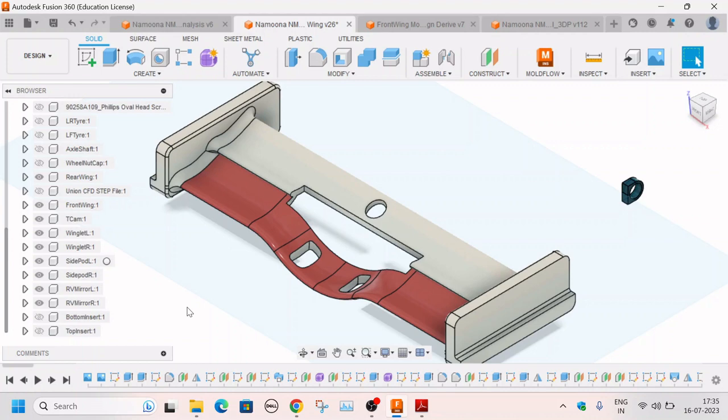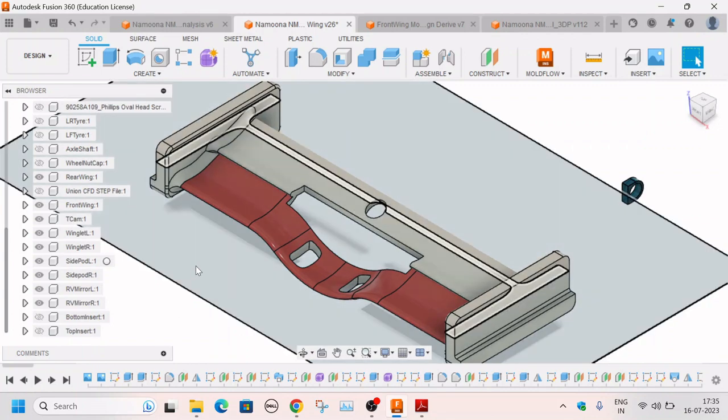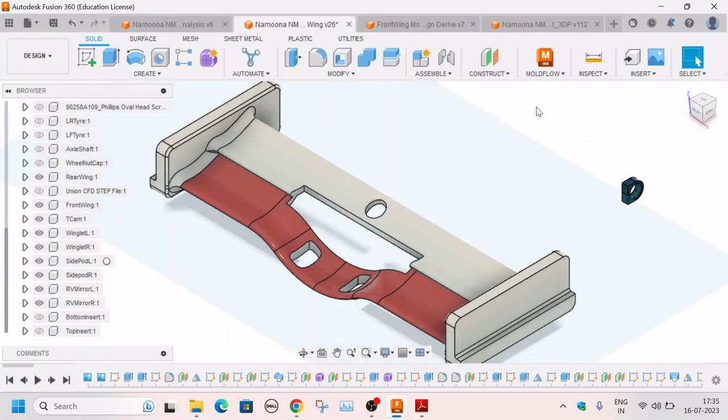So that is one of the aspects, and at the same time any undercuts in the design have to be eliminated. Undercut is any geometry of the part which is intersecting with the drawing direction or the pull direction of the injection mold, which will avoid opening of the mold. So you need to avoid such geometries. When we speak about injection molding in the upcoming lecture, we will look at how you can eliminate undercuts in a more detailed manner.